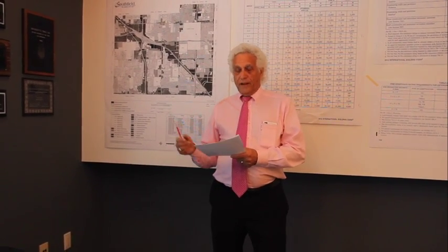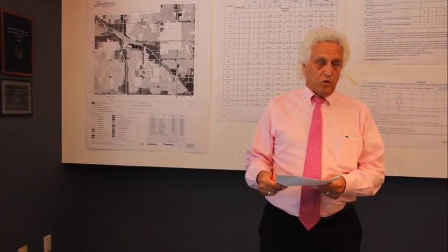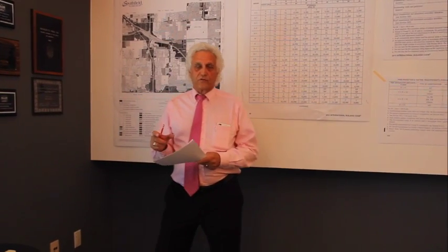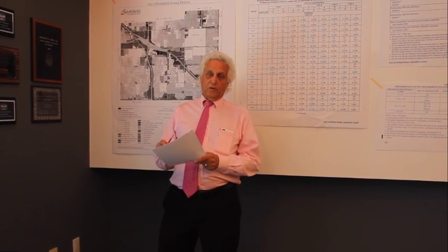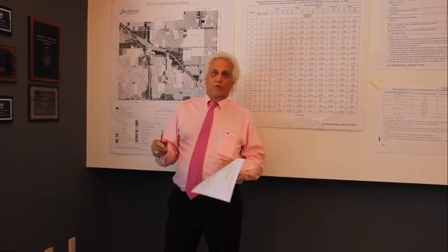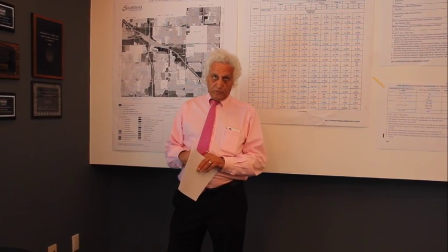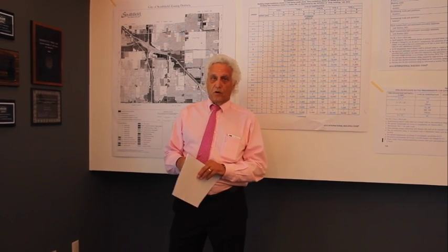So once you've mastered that, then you start looking into the building code. The reason the building code is important is because you need to understand the design parameters of the project before you start actually designing the building. The worst thing you can do is start designing a building and you make it 6 stories, and then you're halfway through the design and you realize the ordinance only allows 3 stories. You're going to have to trash everything and start all over again. So you need to be careful that you understand all those parameters.